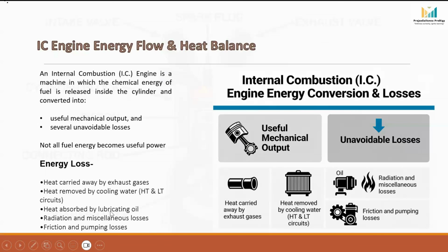Third, lubricating oil losses. Lubricating oil reduces friction, but it also absorbs heat from engine parts. Fourth, radiation and miscellaneous losses. Some heat is directly lost to the surroundings through engine surfaces. And finally, friction and pumping losses. Not all the generated power reaches the output shaft because some of it is lost in friction between moving parts or pumping the exhaust out of the engine.